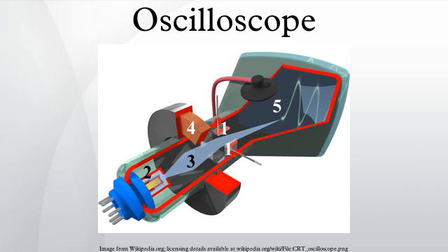The probe connects to an amplifier, which feeds current into the coil to cancel the sensed field. The magnitude of that current provides the low-frequency part of the current waveform, right down to DC. The coil still picks up high frequencies. There is a combining network akin to a loudspeaker crossover network.